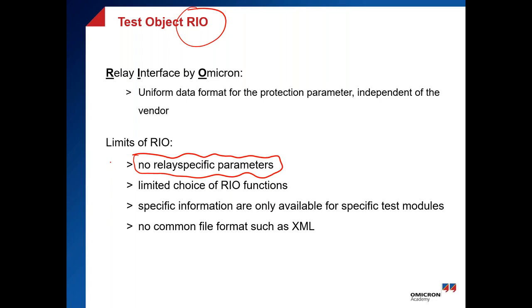And as all of us know, if you have different zero sequence compensation or ground impedance compensation values for zone 1, zone 2 and zone 3, this will affect the relay results and will also affect the relay reach. So if we export the whole characteristic with a single zero sequence compensation, this will affect our test result, because we will test at one value and the relay calculates with another value. So this was the first limitation.